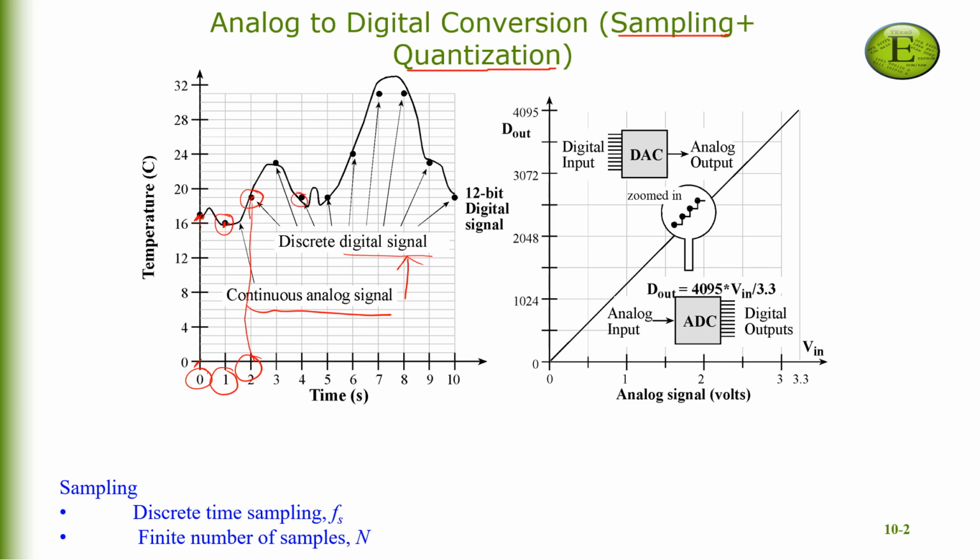Once the signal is sampled, it is then called the discretized signal. The requirement of a signal to become a digital signal will be met when we perform the process of quantization, and that's where the analog to digital converter module inside the microcontroller needs to be configured.